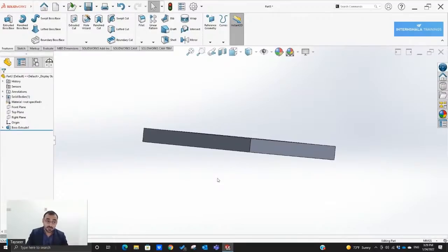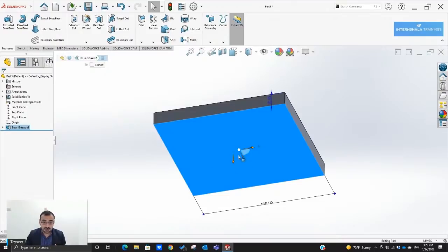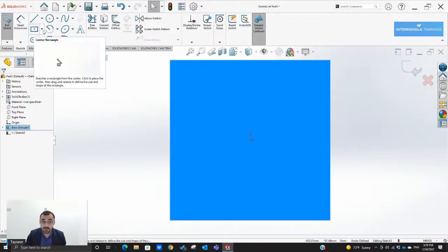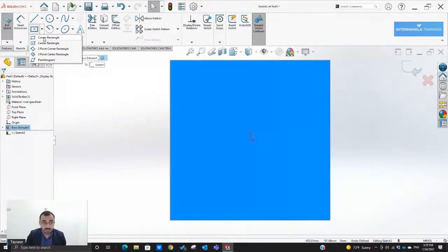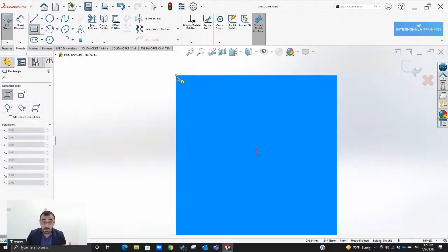Now we're going to do the same thing for the 4 legs of the table. So we're going to do the same process. We're going to do a sketch, and then we're going to do a feature. So I'll go ahead and select this surface for a sketch. Click on this sketch command, and then sketch another rectangle. I'll go a bit quicker this time since we already know how to do rectangles or squares. So I did my rectangle command.